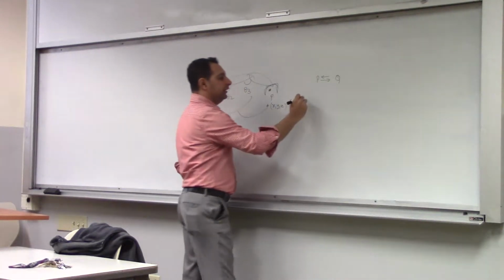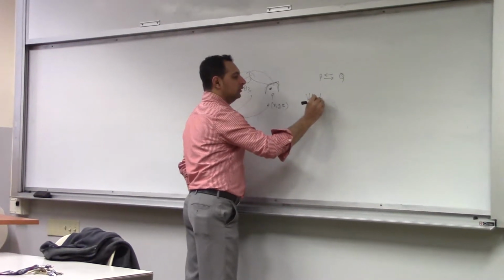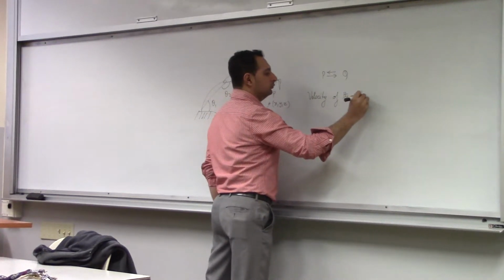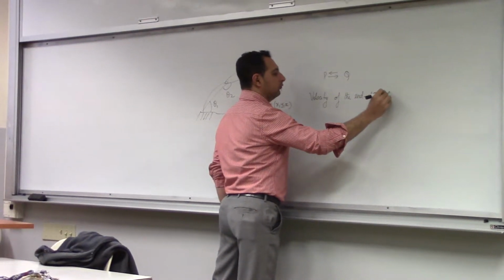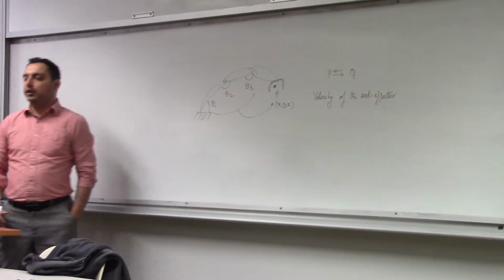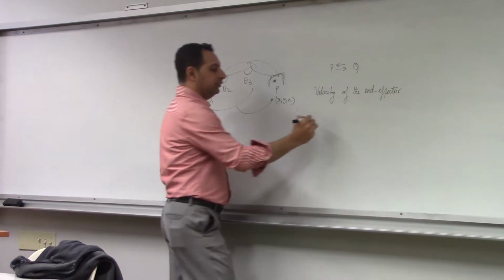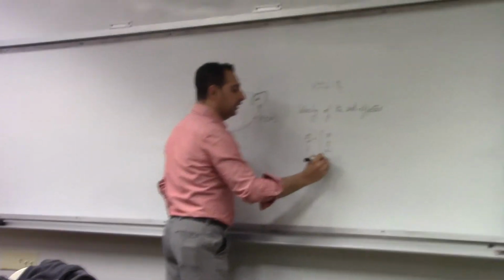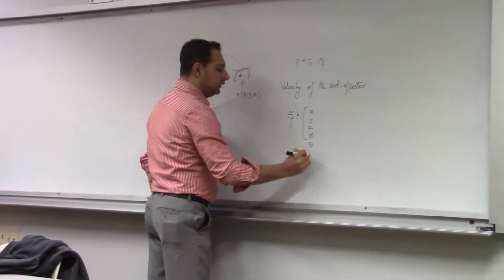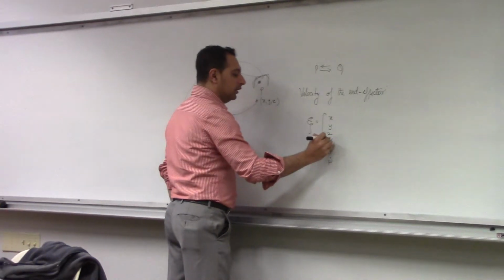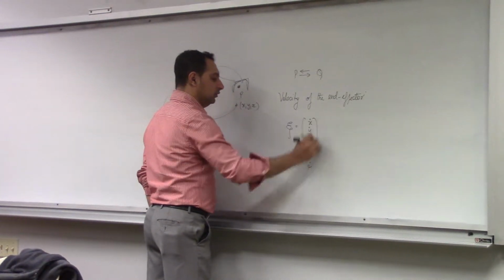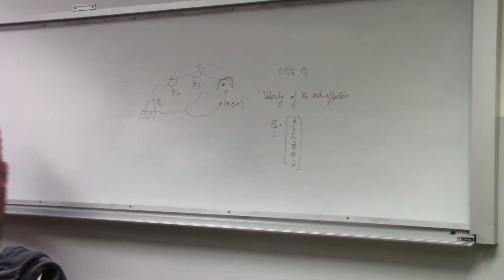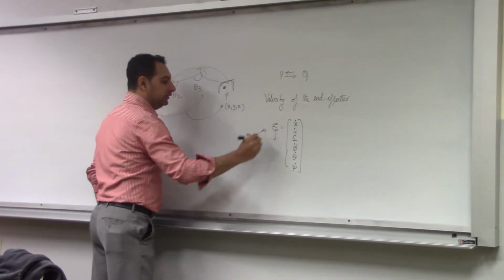Now we want to move on to tracking the velocity. Okay, velocity of the end effector. Normally, for a manipulator that has 6 degrees of freedom, we track both the position and the orientation. We'll write it as x, y, z, phi, theta, and psi, right? Because these are the rates of change, we'll write it as a dot. So eta is your end effector velocities.